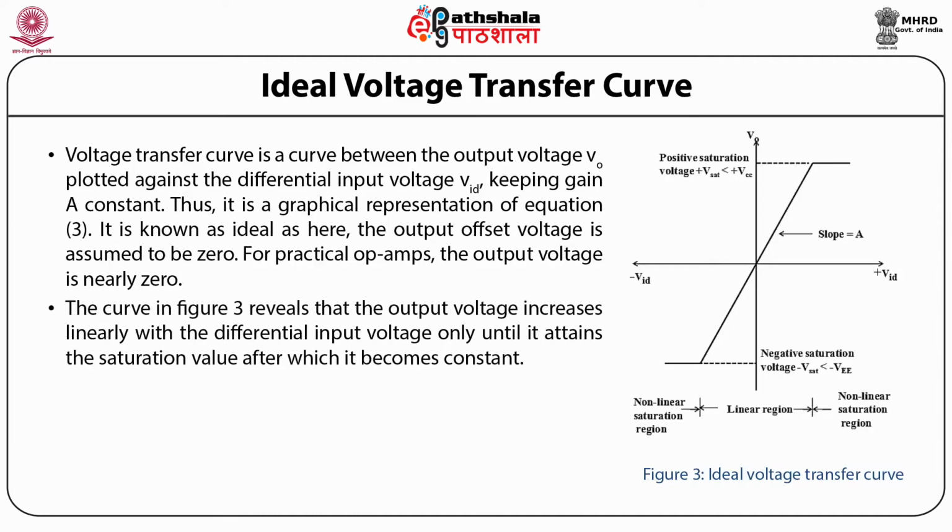The curve shown in the figure reveals that the output voltage increases linearly with the differential input voltage only until it attains the saturation value, after which it becomes constant. The region in which the output voltage increases linearly with differential input voltage is called the linear region.